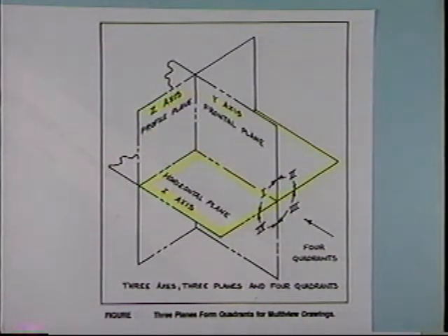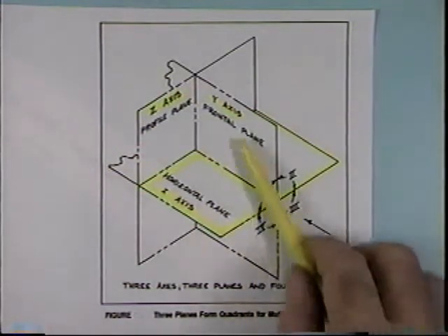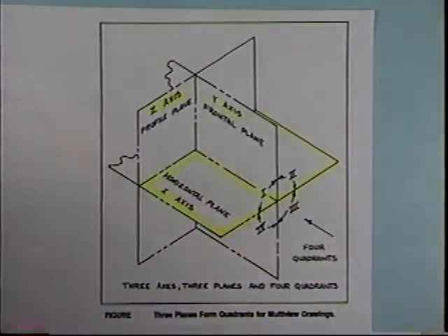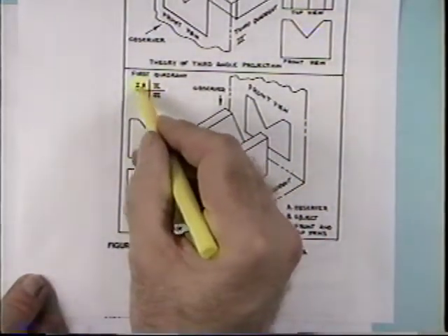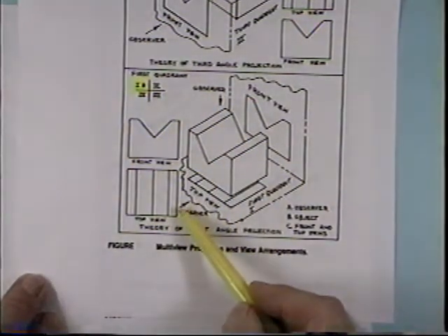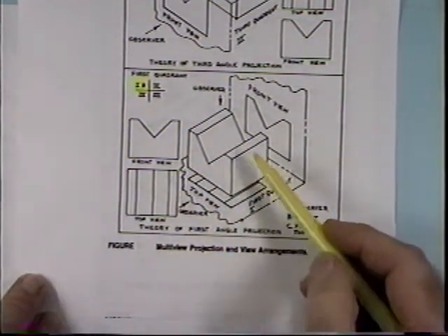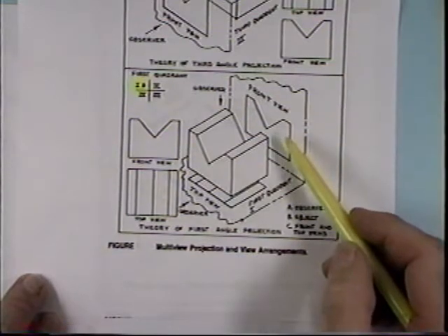So that's where third angle projection comes from. In the other countries, they put everything here in this first quadrant, and when you have that first quadrant, we call that first angle projection, because we have the observer, we have the object, and then we take the object and we put it onto the glass plane.